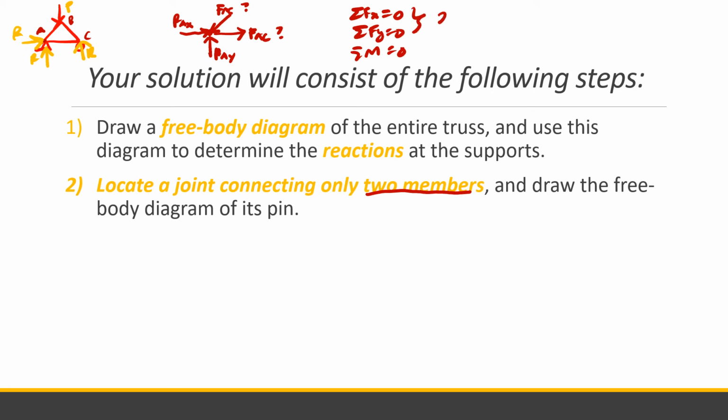So we have only two equations to use, meaning we must also have only two unknowns when solving the problem. That is why the first step is to choose only two members, so that we have only two unknowns. Two equations, two unknowns, so our equation is solvable.